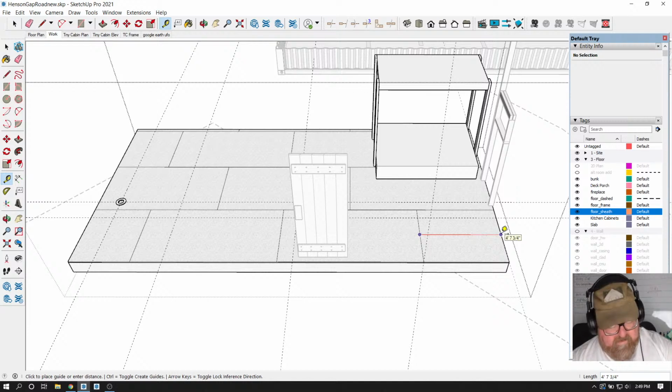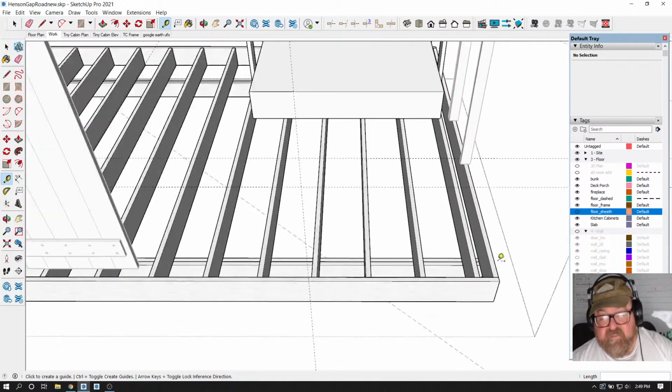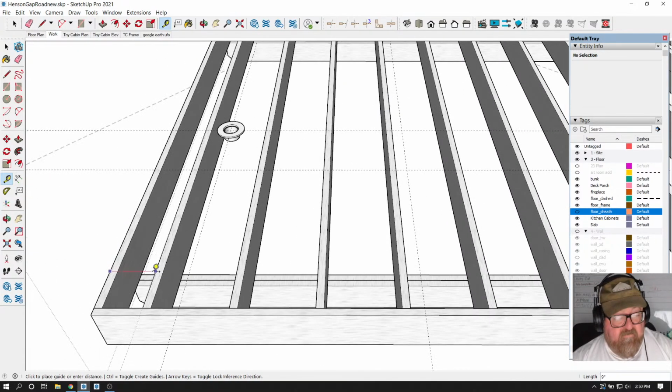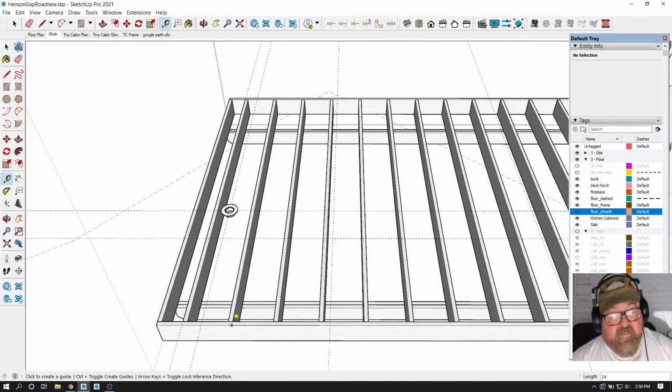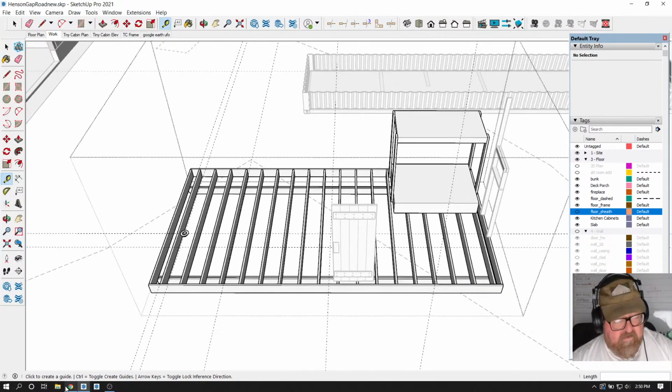Because what you want is, the piece that you cut off this end, since it's 24 feet long, can go down here. And that's why it doesn't matter that these are 16 inches from the end, right? So when I start my layout, I will start it out either from this end at 9 inches, and then set ahead, what we call set ahead 16, you see? And then all the joists and everything will be in proper layout. Let's see if we have any questions.